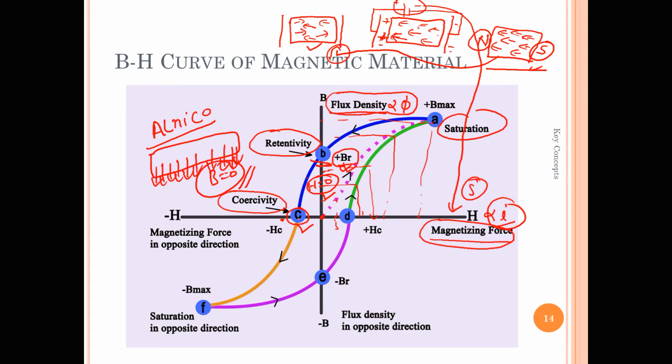What's the negative point? That the coercive value is very much lesser. It means if you have this zero point, and this one is very close to this zero point, then with a very small amount of negative current or a temperature, that's also related with the temperature that we will discuss later. Once you have a temperature rise, this particular coercive point starts shifting toward the origin. So if the temperature rises, the magnet gets demagnetized. So what is the negative point?